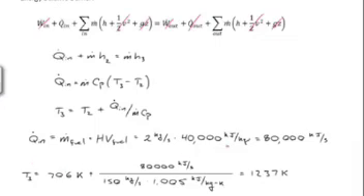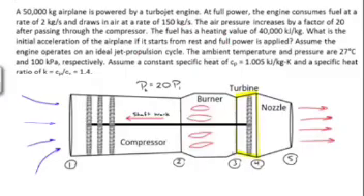What we come up with is T2 plus 80,000 kilojoules per second divided by the mass flow rate of air times its heat capacity. And we come up with a temperature exiting the burner of a little over 1200 Kelvin. So we're working our way through this problem. We know the temperature leaving the burner. Let's focus attention now on the turbine itself.